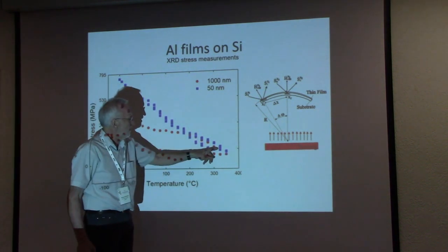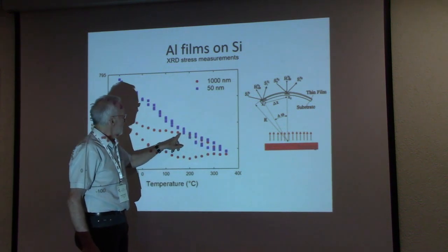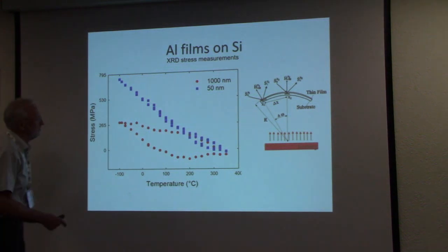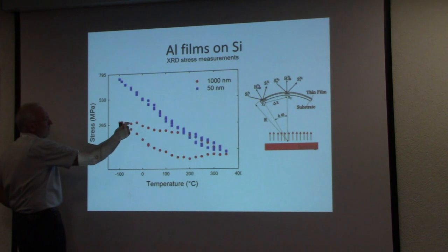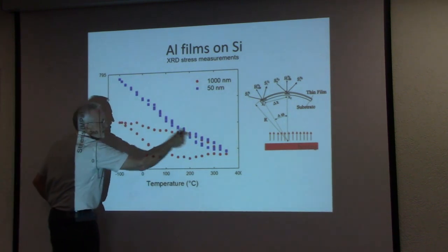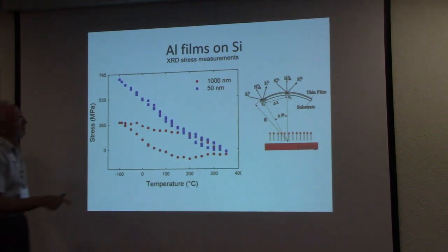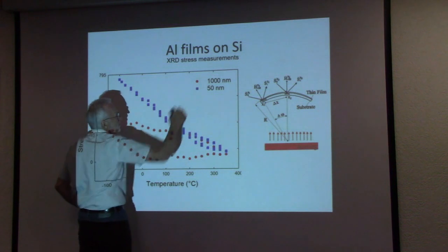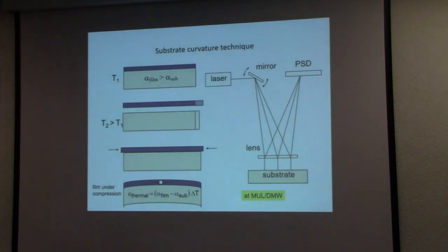And when we cool down, the stresses change again, at first elastically, but then the plastic yielding starts in the opposite direction, and then we get a tension yielding in this case, exactly the opposite. And this happens in each heating cycle. But when you have this high strength aluminum alloy, then you have nearly linear elastic behavior. So the technique is quite simple.